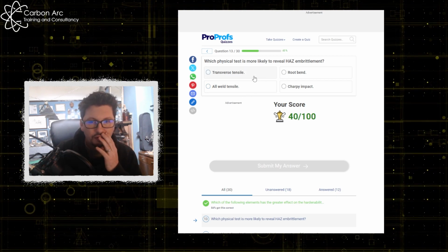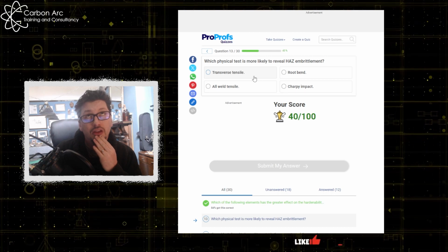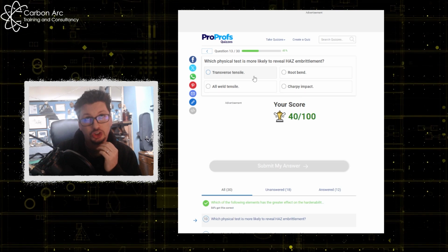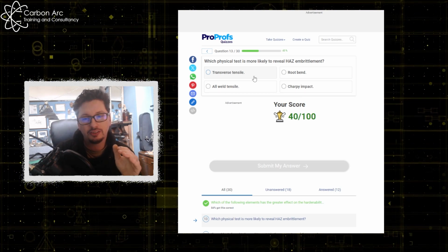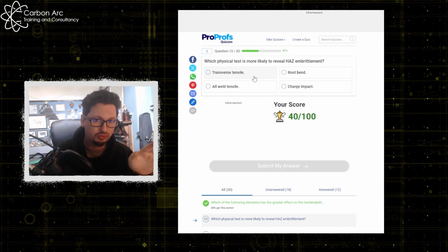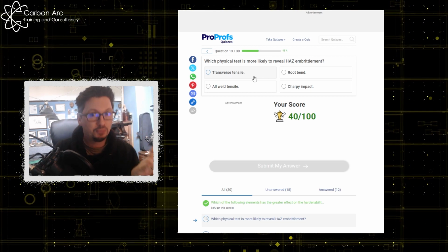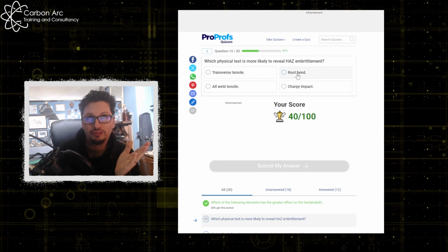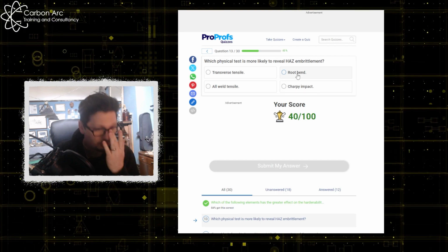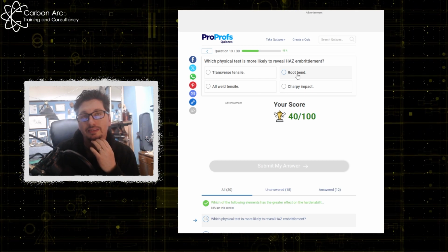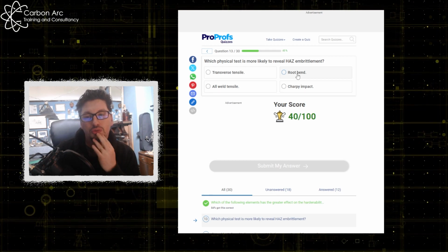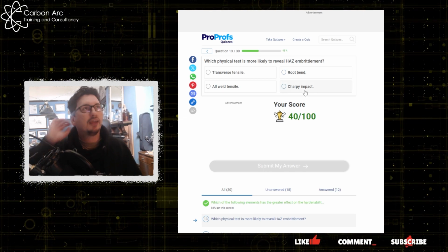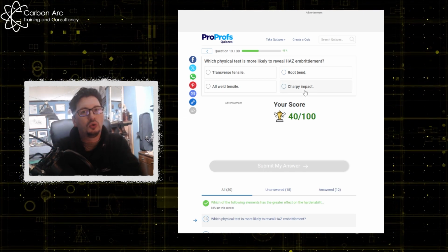Okay, transverse tensile test, if the tensile test fails in the heat-affected zone and it shows a brittle fracture face, so no deformation, crystalline brittleness, so potentially. A root bend could be if you bend it through whatever degree, 90 or to 180, and it snaps in the heat affected zone. That would show heat affected zone embrittlement. And a Charpy test would show embrittlement